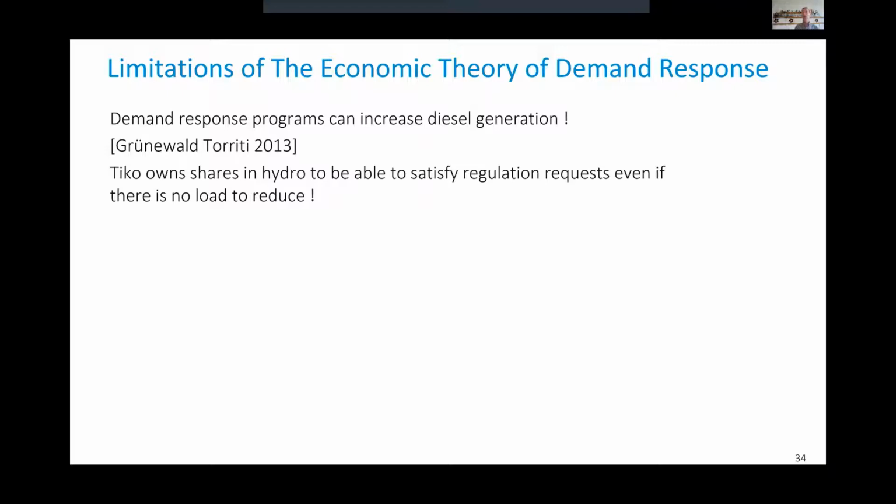And then once you have a battery that you can use as backup power, you can also use it to provide regulation services. I've shown an example with the microgrid on the EPFL campus that provides primary and secondary frequency support. That's an example. This battery could be present because we need it for a data center, for example, for backup. And if we have it, then we can also participate in supplementary services.